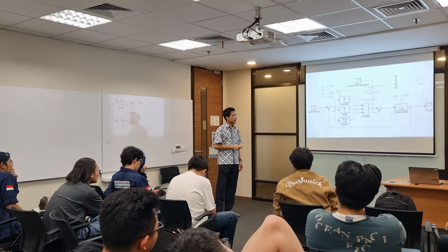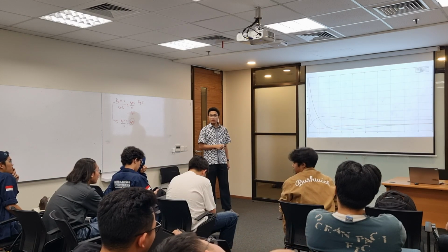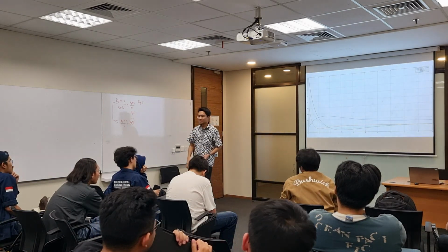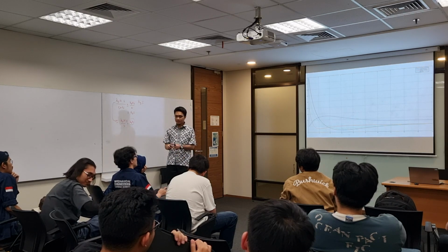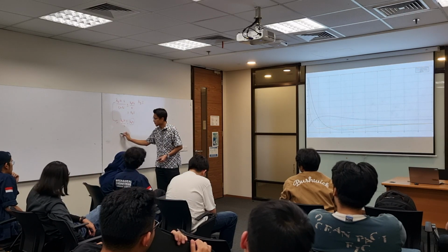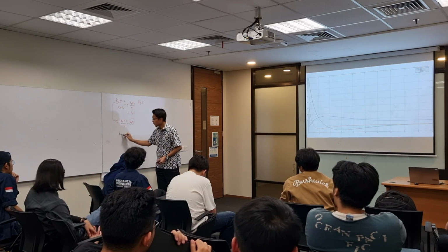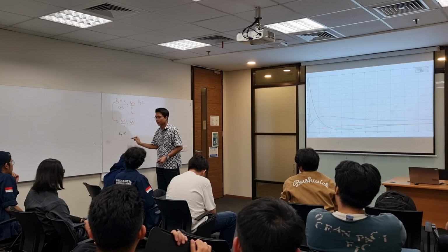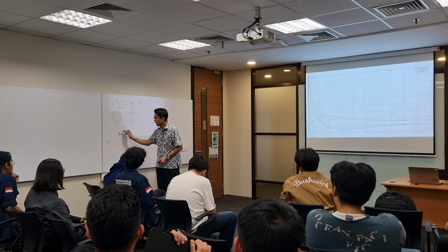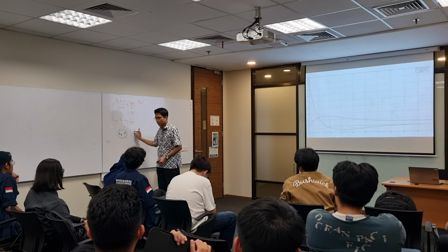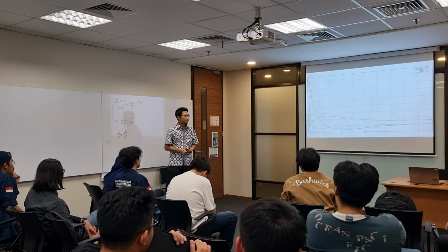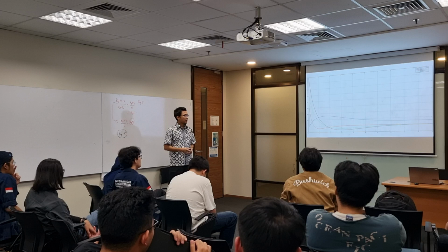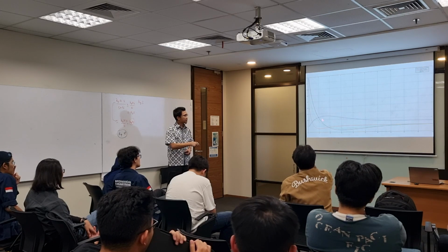Yeah, good question. The first thing is that proportional control action only multiplies the error. When the error is 0, then the control action will be 0, right? So which is why the proportional control action is 0 when the error is 0.